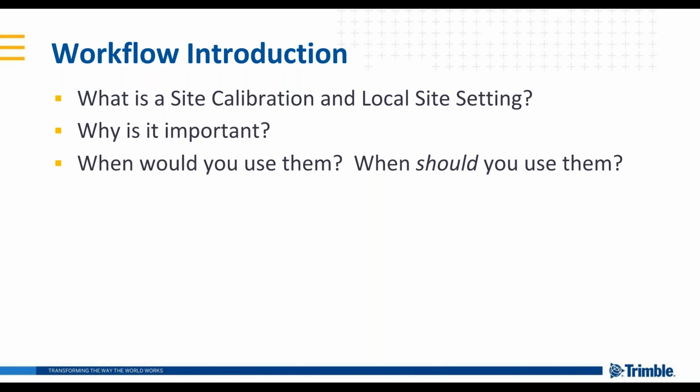Site settings is licensed to base editions of TBC, whereas site calibration is licensed to the intermediate versions. So if you have an intermediate version or above that you're working on, then you should be able to recreate all the workflows we're going through here today. One last note is that this Power Hour deals with coordinate transformations, and a lot of that has to do with the difference between grid and ground coordinates.